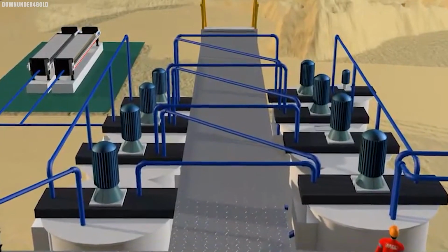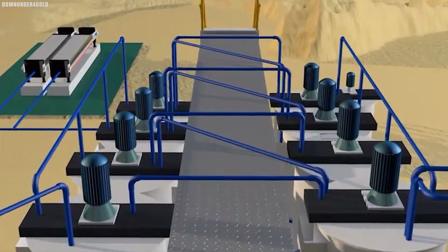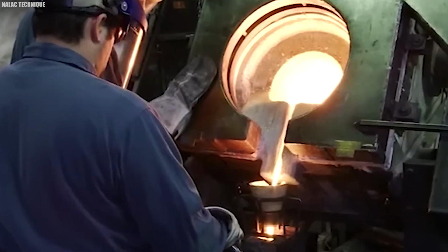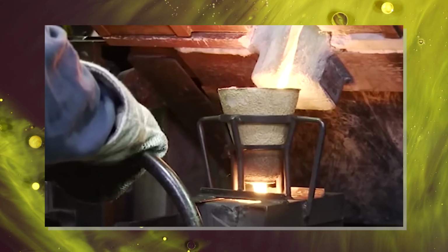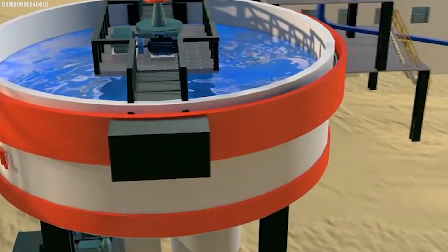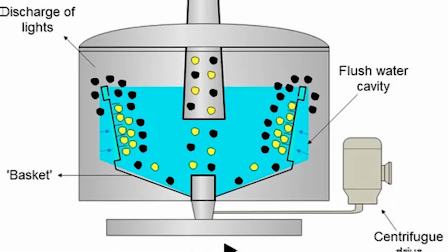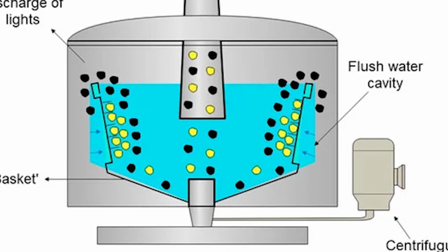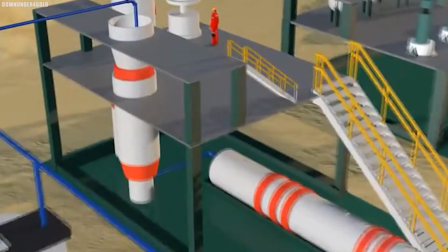These are spiral-shaped devices where ore slurry is fed to the top and flows down, with heavier gold particles moving toward the center, and from here they are made ready for the jigs. Think of these jigs as sieves that pulsate water through them, helping separate heavy gold from lighter waste. Then flotation is followed, which is an intriguing process where bubbles do all the heavy lifting, literally.